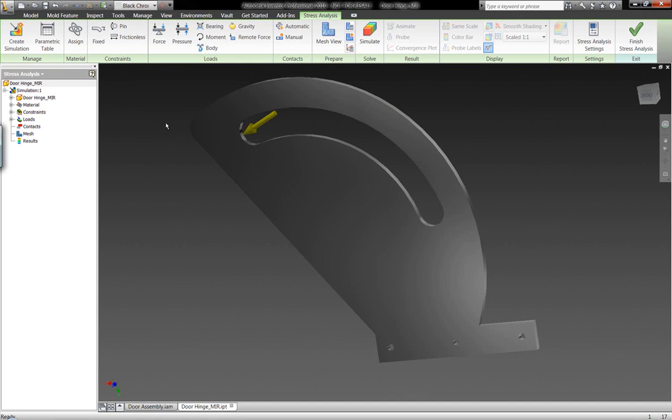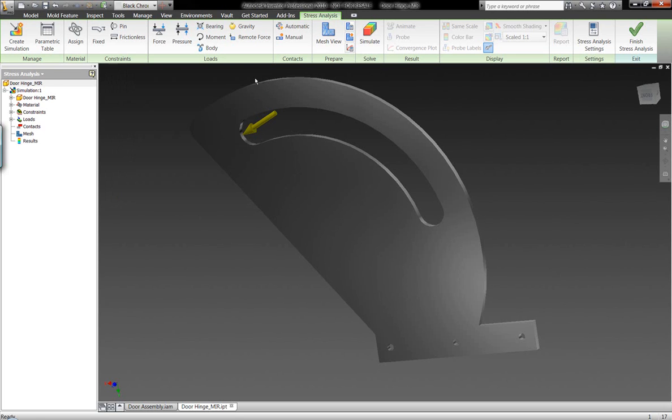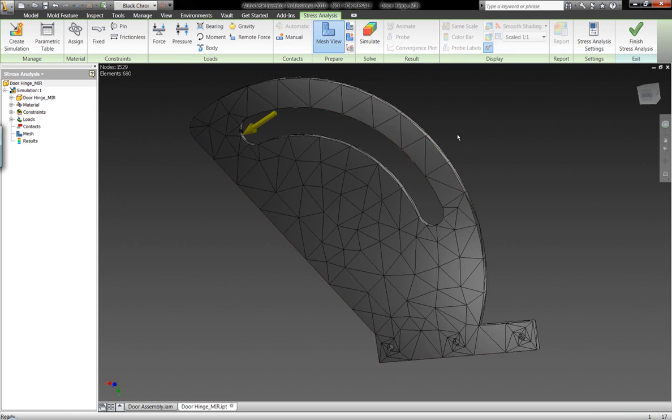Within my assembly, I have capabilities of doing that as well, using some of the simulation tools within Autodesk Inventor and passing those forces directly into a part. I can also analyze or approximate those different components within this part environment as well, individually. I have the capabilities when working with the geometry to control what size mesh is being generated on the model. I also have capabilities to use local mesh control on the geometry to apply a series or a location of where I want maybe a more detailed mesh region on my component. I can also use the default mesh settings and mesh my component.